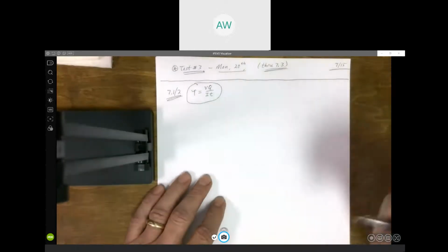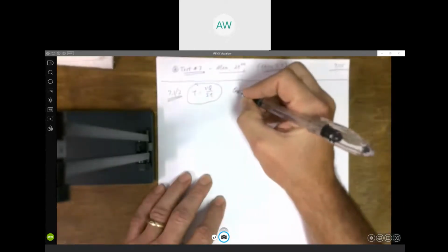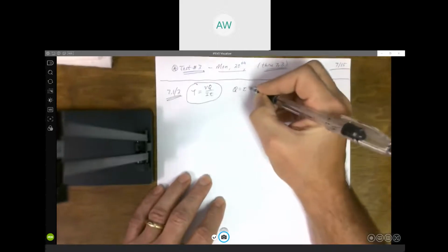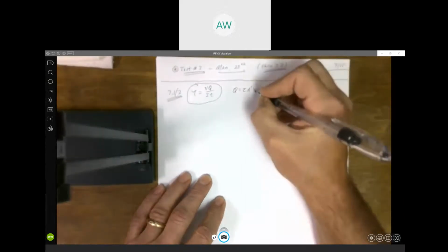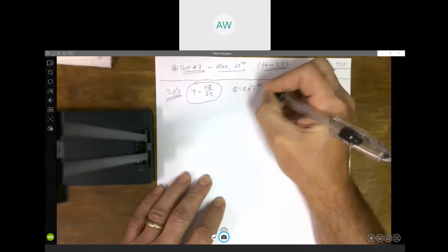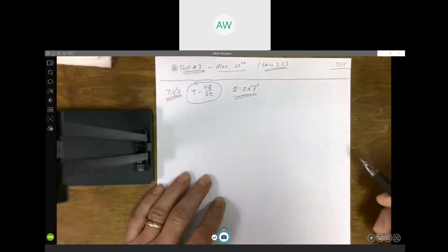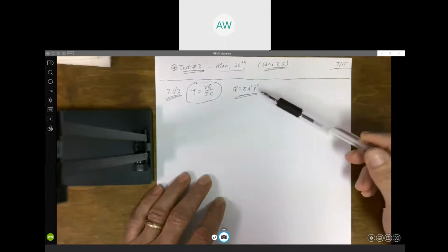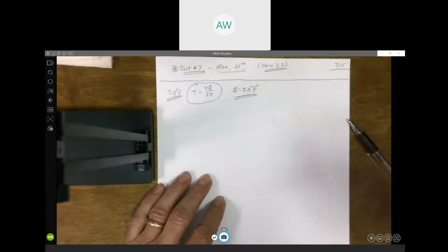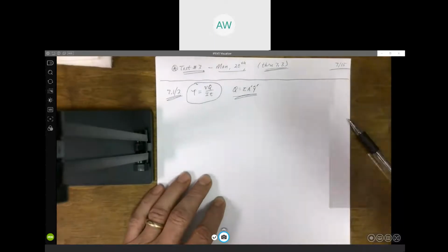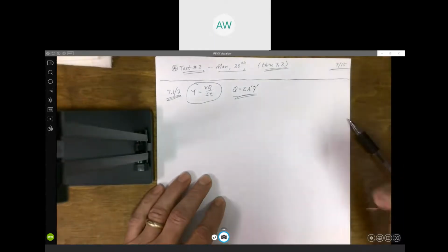Q is the first moment of area, and remind everybody it's the sum of, using the notation he uses in the book, A prime times Y bar prime, where A prime, this is the area above, on that cross section above y prime, where you're calculating the shear stress.